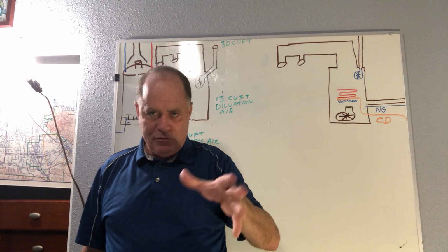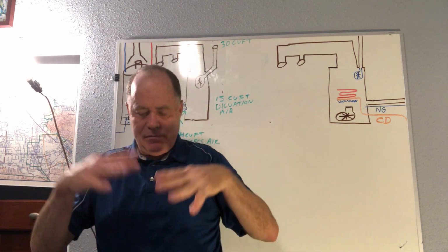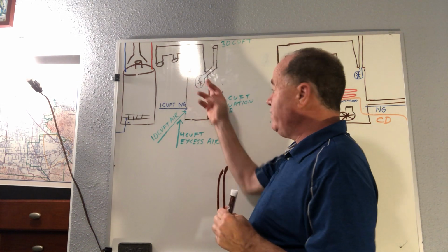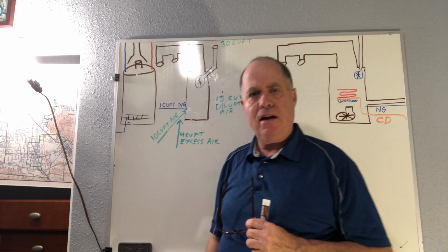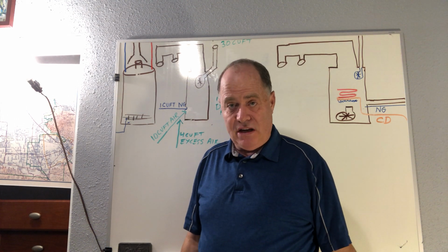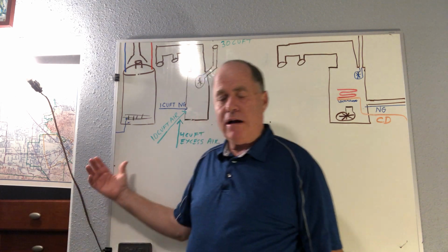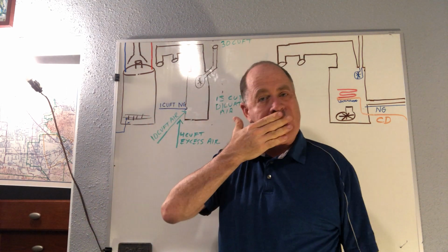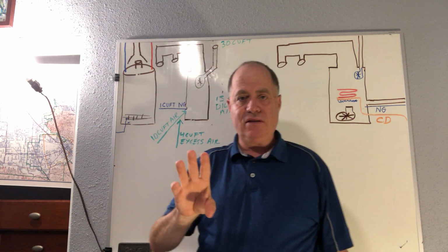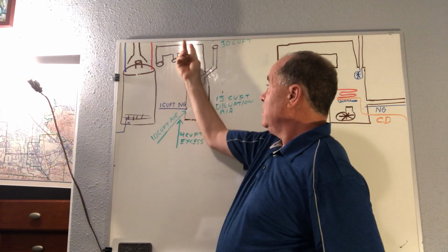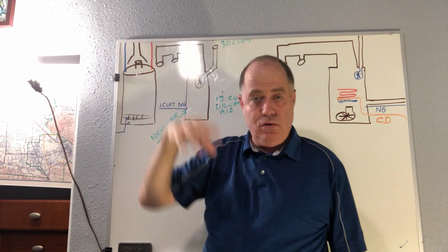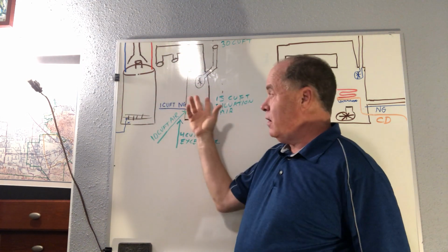Okay? So I'm trying to get you more on the concept, because there are a lot of changes going on right now in our industry. You have these furnaces, and these are like 82% efficient furnaces. The natural draft ones are more like 70%, where if you had a big natural draft furnace with 100,000 BTUs quality of natural gas, the amount of heat you're getting out the pipe into the plenum might only be 70,000.